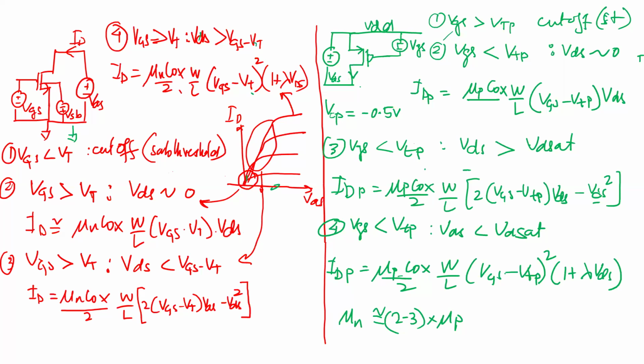So that's where the charges get trapped. And because of that, those charges affect the channel, almost like a quantum effect, where they seem to release into the channel and grab from the channel as low frequency noise. So as you go lower and lower in frequency, the amount of charge which gets released and trapped as noise increases. Okay, and for low frequency, that's what is important to us.